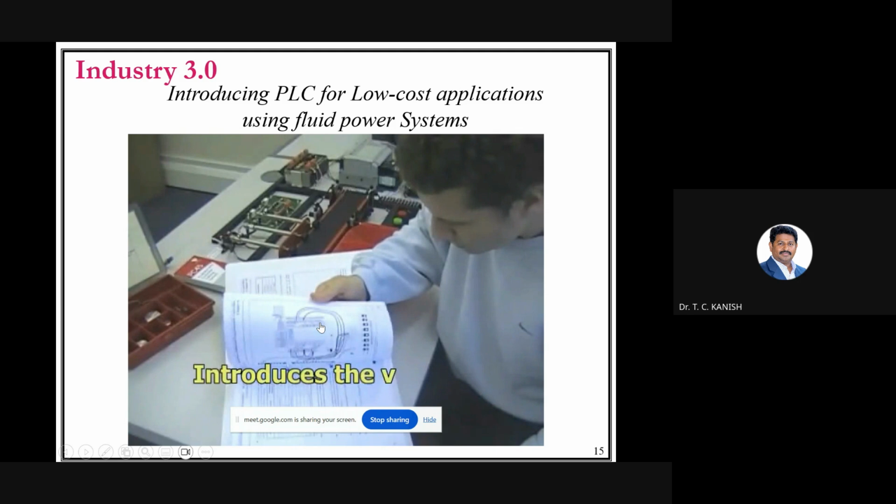When you are moving to robotic systems, we can develop different types of robotics. You can use servo motors, or any of the electrical motors for each and every joint, and then you can obtain the motion. Otherwise, you can go for hydraulic or pneumatic systems for your robotics arrangement when you are developing your robot. We can use either pneumatic, hydraulic, or any of the electrical drives. Simply you can use some pneumatic pressure, or if the load is huge, then we can go for hydraulic and develop our own robotics.